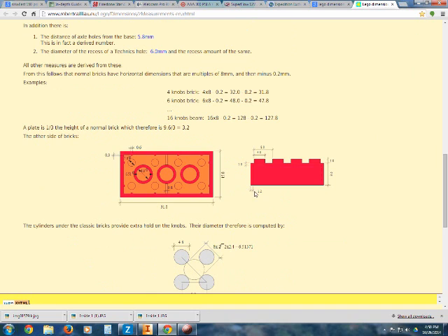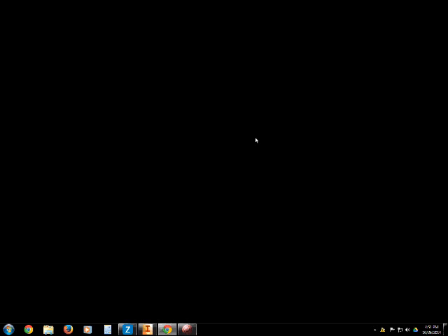So right here it tells you that the sidewall thicknesses are 1.2 millimeters and that top wall thickness is only 1 millimeter. And we could do that by drawing another rectangle. We'd have to create another sketch plane here and then draw this rectangle, making sure the dimensions, and then when we extrude it, just extrude it back whatever this distance is.